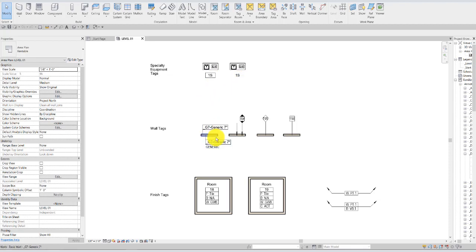We have our wall tags, which will show the type name and the description, and for both of these the box will shrink or grow to accommodate whatever amount of text you have to describe or name that type. We have the leader, which is used for when a tag needs to denote 2 or more walls. We have the standard tag and then the diamond and square tags.